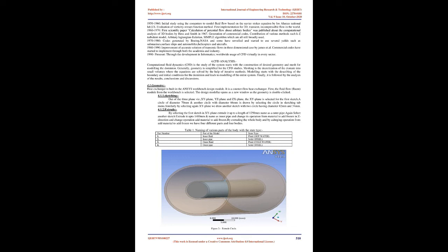Cannon et al. studied heat transfer through the double pipe heat exchanger with annular fins. Three different configurations, annular ring, spiral rod, and rectangular projection, were considered on the outside surface of the outer tube. Experiments were done with varied mass flow rates. It was observed that the heat transfer rate was increased for a finned tube. Fins with annular rings showed better performance than the other methods.